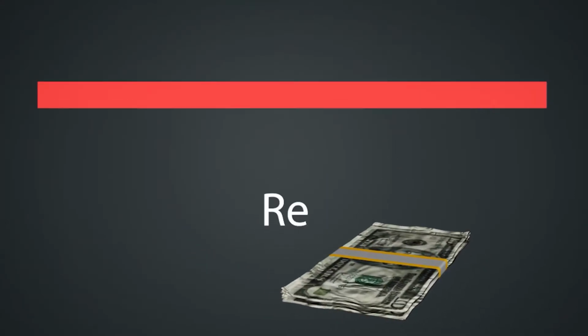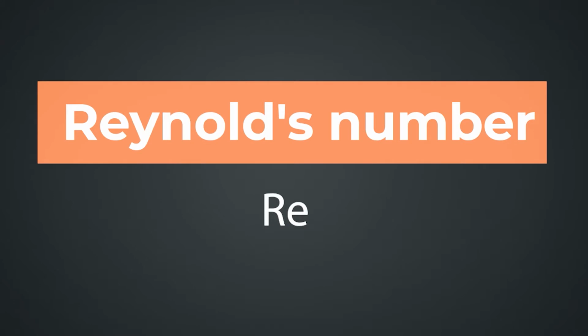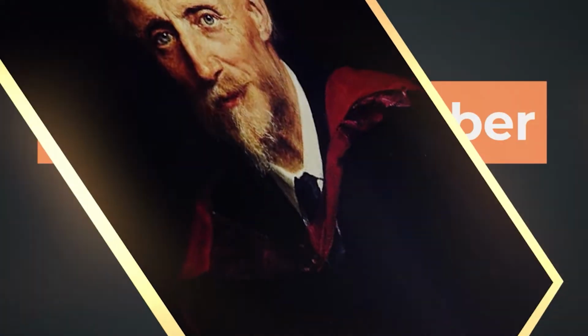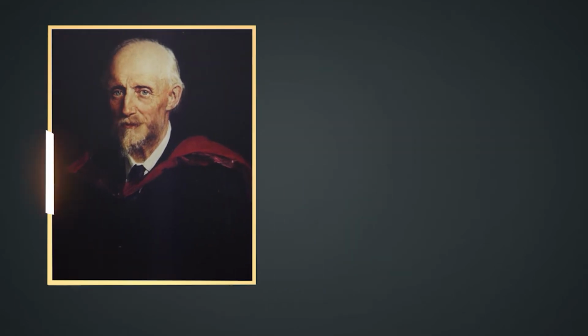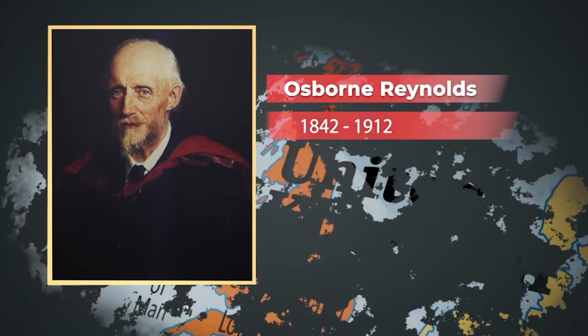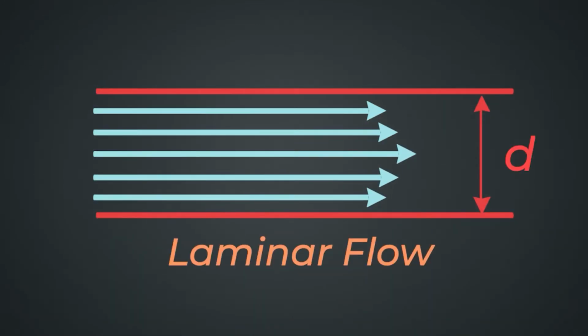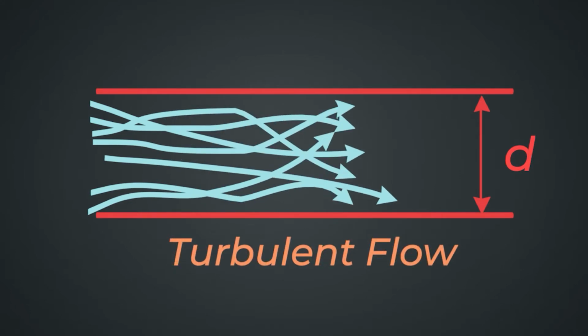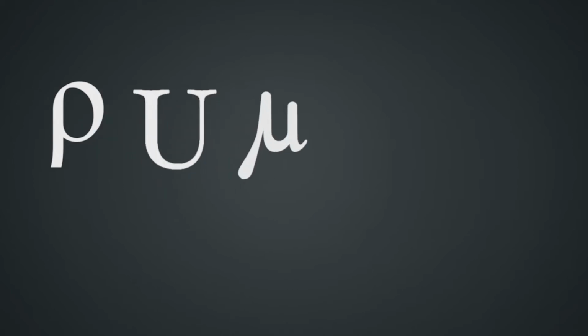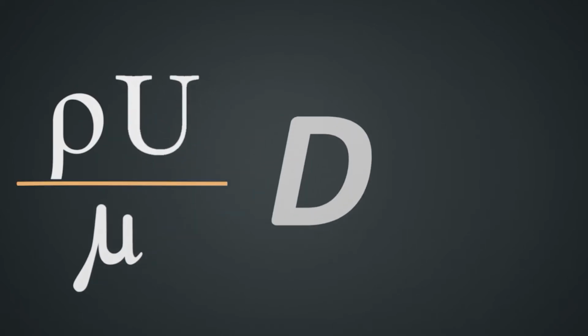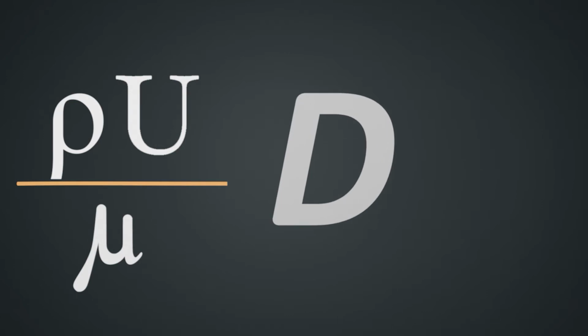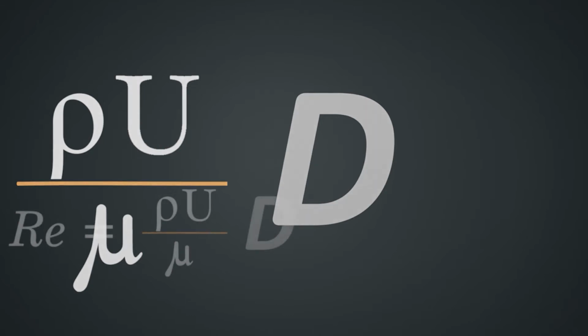I'd like to start with Reynolds number as it's the most used quantity, named after the British physicist Osborne Reynolds, who performed his elegant experiment in 1883. Reynolds brought to light the fact that going beyond a certain threshold deteriorates the nature of the flow. This threshold is a combination of parameters which make up his famous formula: density, velocity over dynamic viscosity of the fluid, multiplied by the tube's inner diameter carrying this fluid, say d.